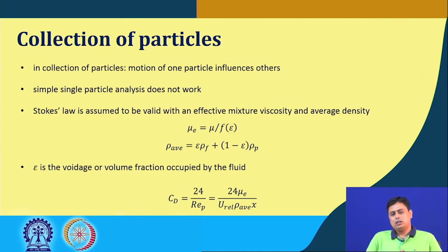So, the settling operations we can operate in two different ways. One is batch settling, where we just put certain particles in the fluid and we wait for them to sediment, for the settling to reach its final stage. And the other case is a continuous operation, which is called continuous settling. So, we will see these two in detail in this section. Now, before that, as I said,